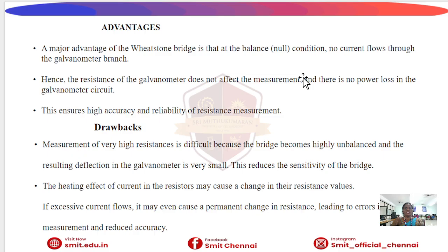One major advantage of Wheatstone bridges is that at a balanced condition, no current flows through the galvanometer. So the galvanometer resistance does not affect the result. Also, there is no power loss in the galvanometer branch. This gives high accuracy and reliability.